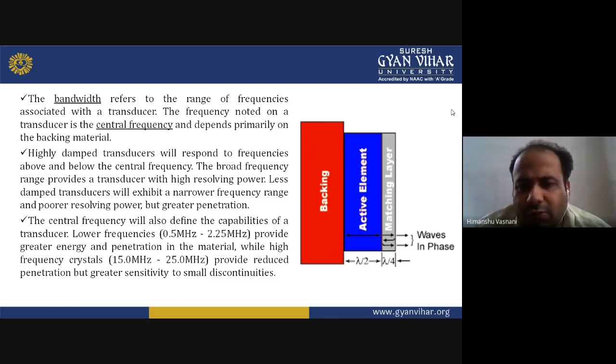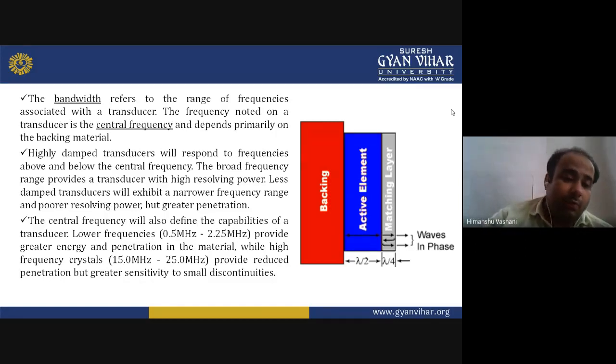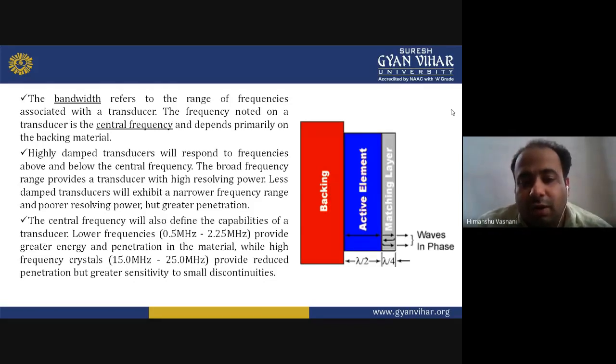If you have lower frequency, then you will have more penetration in the material. If you have high frequency, then you have less penetration, but sensitivity is good for defects and discontinuities, which we automatically require because our purpose for ultrasound testing is to find out the discontinuities. So for this we require high frequency crystals.